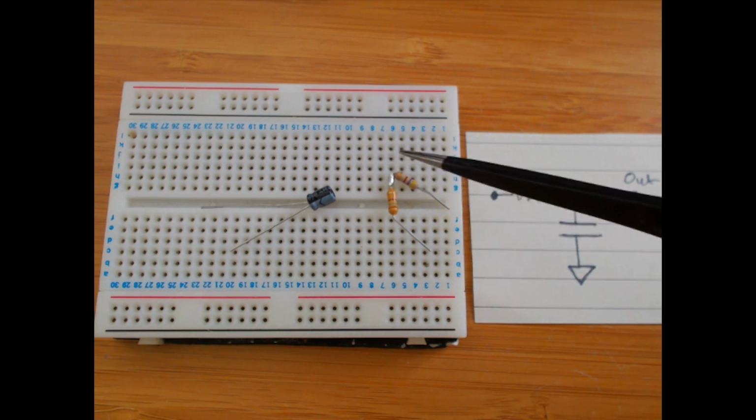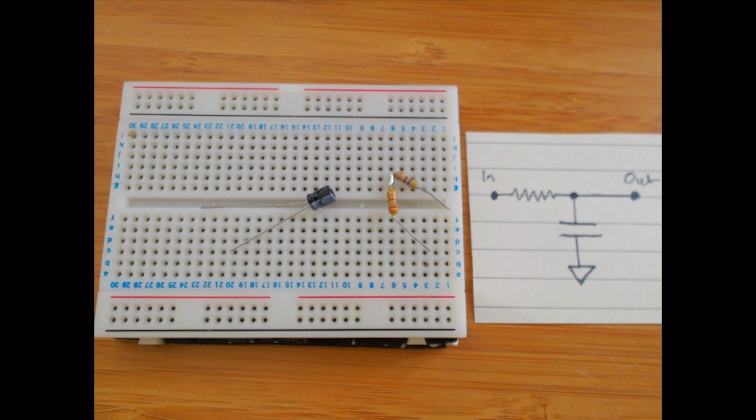What this will do is create a filter of around 250 hertz. Now, it won't cut everything off above 250 hertz. It just starts to attenuate it, to dampen those signals off. It will also leave some noise in, but this will give us something that keeps enough of the original wave and lets us get to the essence of that spinning cube. So let's actually build this on the board now.